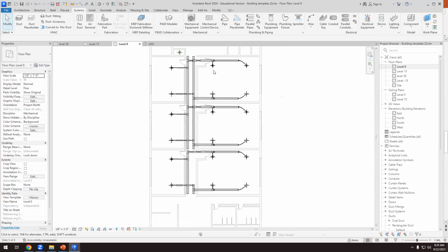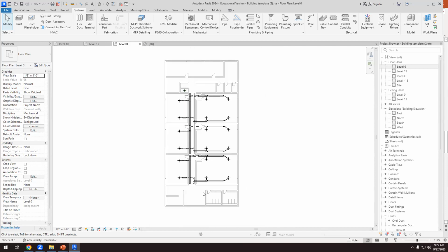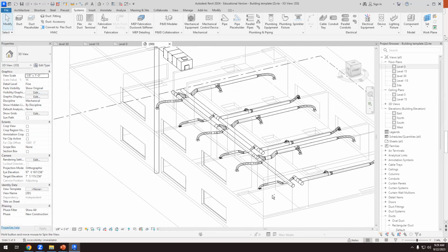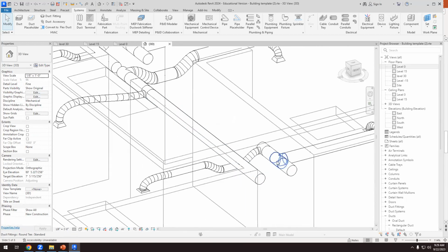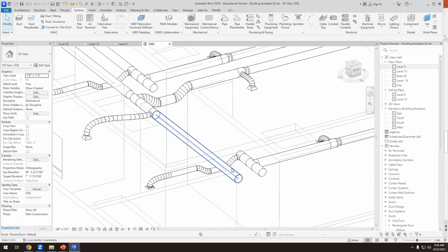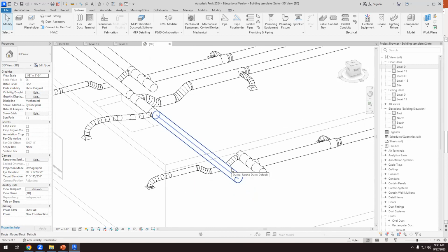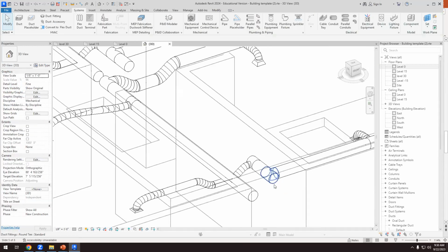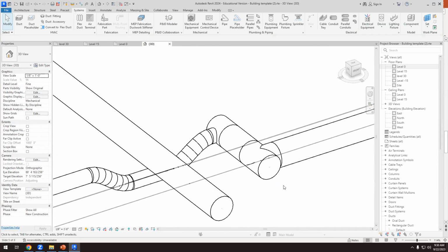Okay, I'm copying. Once I'm done with this, I have copied this 3 times. And now I have to finish the ducts because this is not open anymore. Here I don't have a T. Here I will have the elbow. So if I have an elbow, I have to delete this one. And that's wonderful. Okay, that's amazing in Revit.